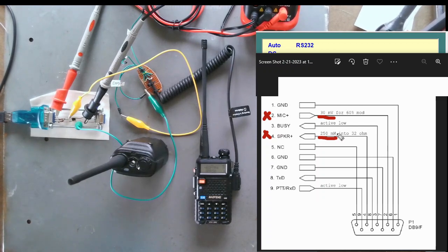depending on what software you want to hook this repeater to, you may need to lower the volume. Now the problem is, as you know, these repeaters do not have a volume control. So we're going to have to add a variable resistor to the circuit. That's going to be the audio part of this video series.